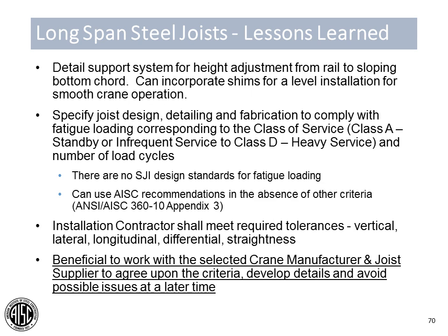Also try to detail the support so that you have height adjustment to accommodate dead load deflection in your superstructure. You could either utilize shims or through bolts with adjustable nuts to provide some vertical adjustability. And also, if you're designing these runway systems within a joist and joist girder type structure, there are no SJI design standards for fatigue loading.